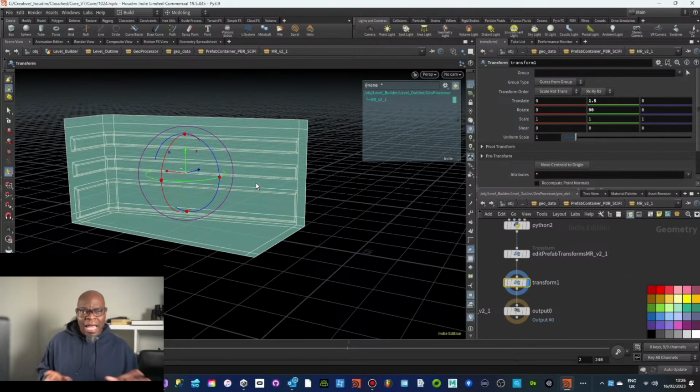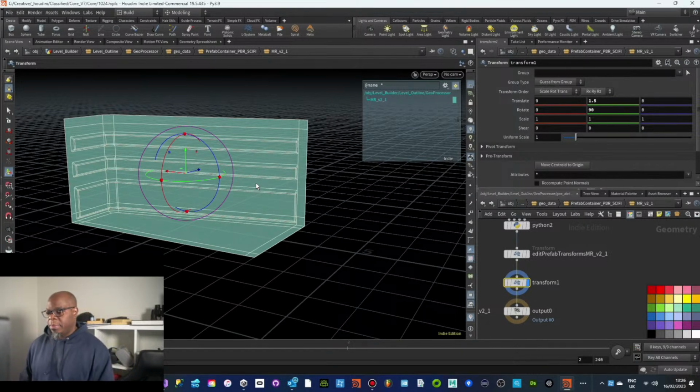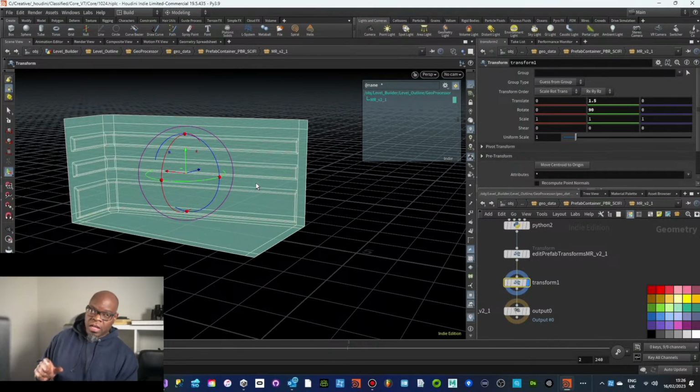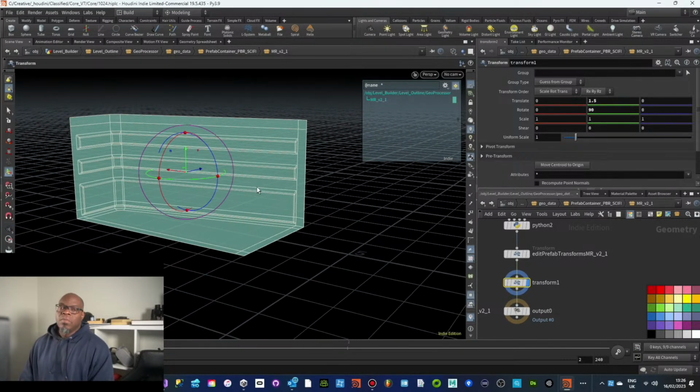Remember, this is FBX settings. So if they're custom settings that have been made within Unity, you're not going to just automatically get them into that application. You need to write specific logic to interpret what you're working with, and then work with it like that. So in this instance, I've been using the bounds component, which will give me the extents, and then asking it for the centroid, which is going to give me a vector at the center of that asset, and that's how I'm reverse engineering it to get the pivot point information, right?